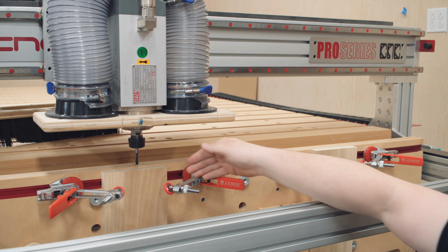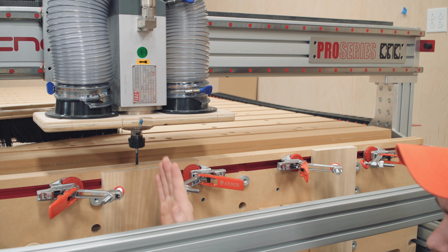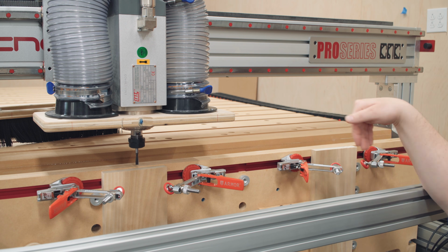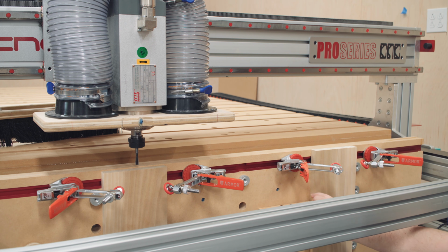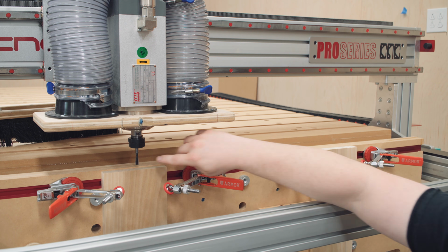So on the left side of this board is a series of dogs in a vertical orientation to align the board vertically. The right side of this board is another set of dogs to align it vertically. And of course, the table surface aligns it in the Y direction. So all I need to do now is set the height to the specified height.